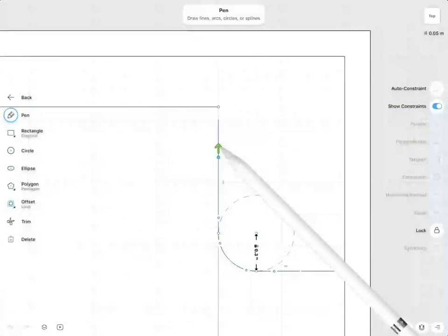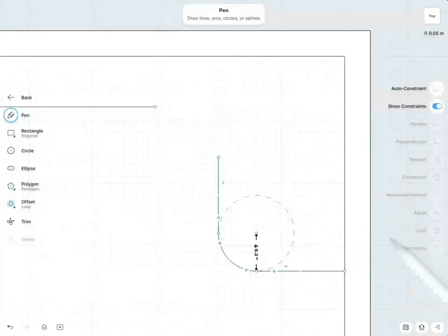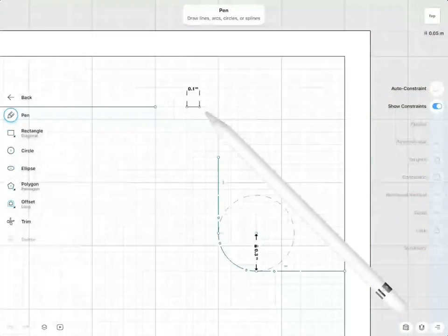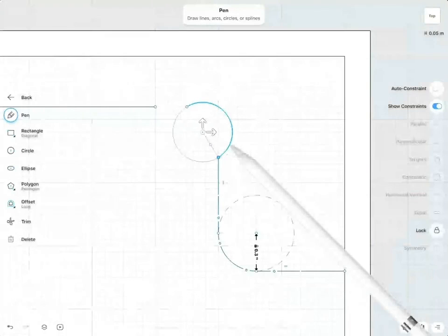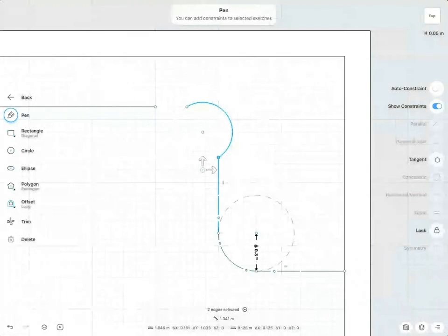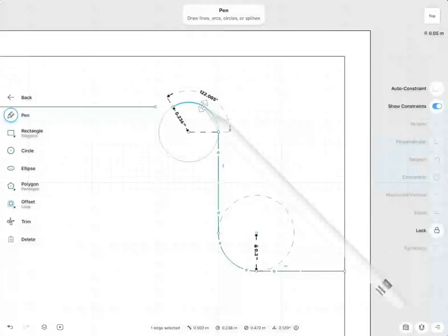Which means now when this is 0.3, I want to have the same there. This point, I will have to move down a little bit. This line I will make horizontal. Select this point, move it to the right. And then I can create another arc. Connect this, for example, there and there. Then again, I will do a tangent. You see that adjust that part.